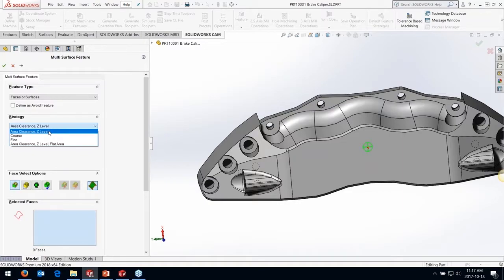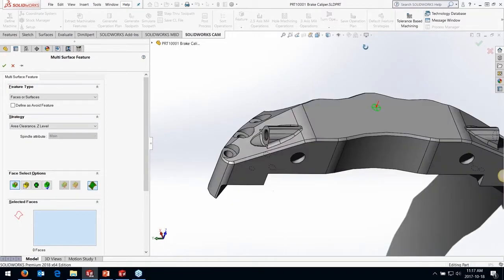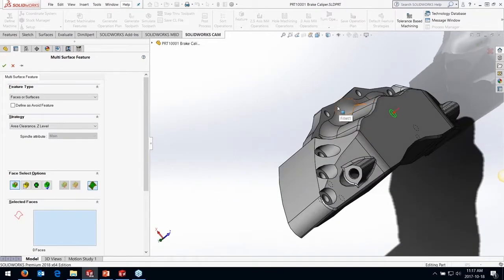And then essentially all I have to do is hit generate operation plan, and it's going to look up in that database those settings that I've been working with previously and generate a series of operations for me. So I've really clicked a few settings, but I've got an entire program that I can now generate the toolpath on and simulate that data.